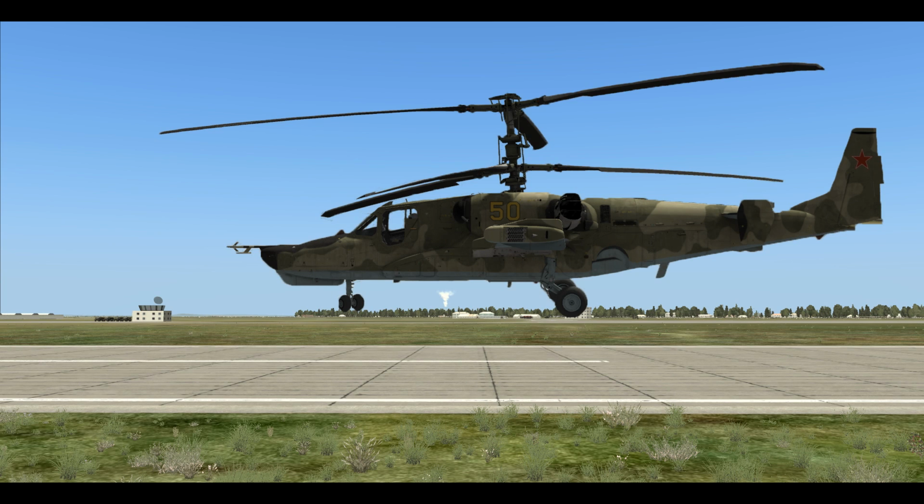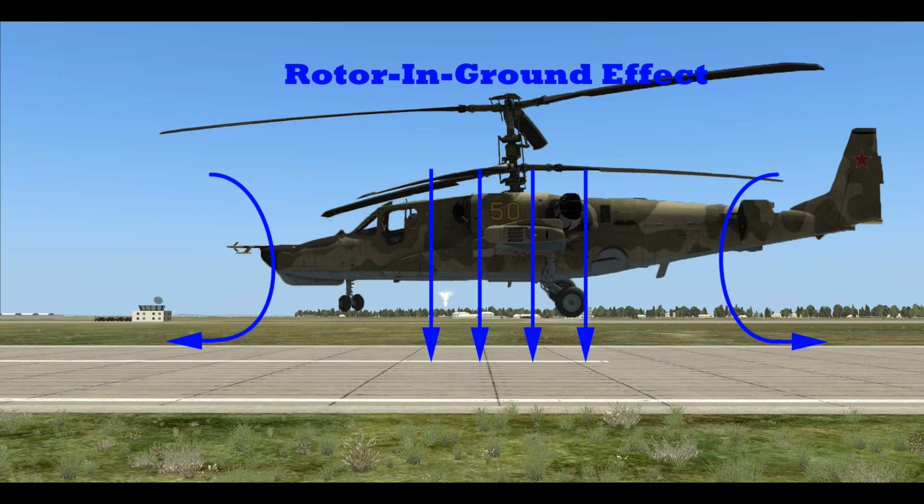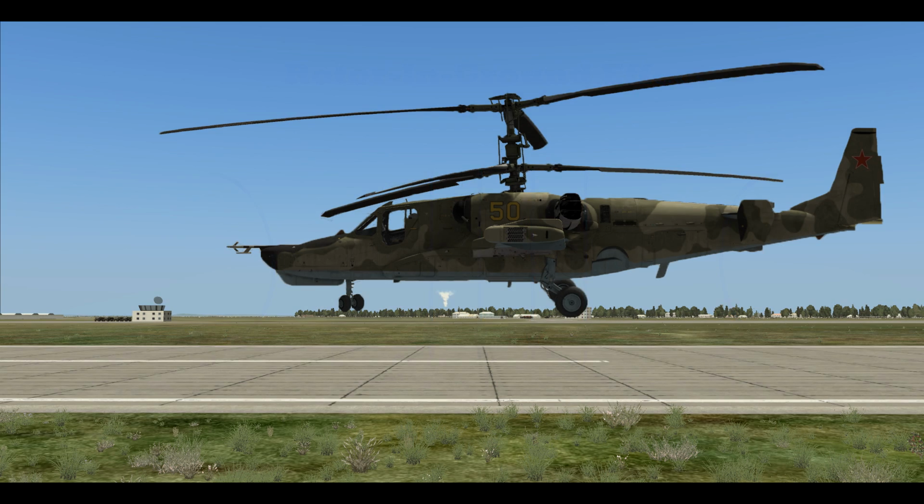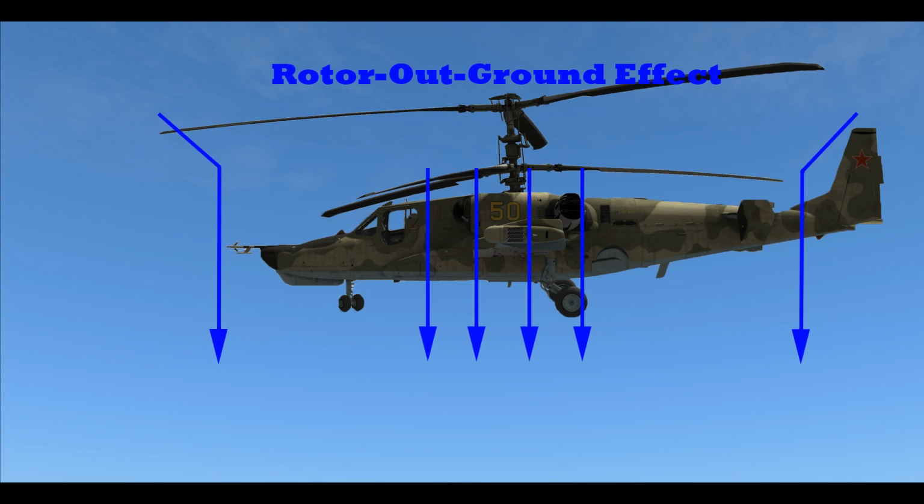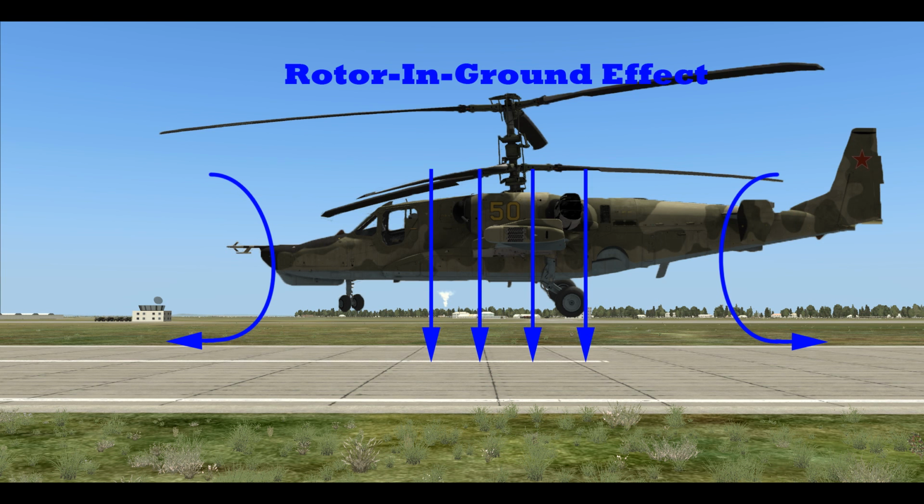Before we are taking off, let's briefly talk about this thing called ground effect. Ground effect is something that will happen when you come too close to the ground with your aircraft. The airflow is changed, it's not going down anymore, instead it's bouncing back from the ground, generating more lift for your aircraft. So you have to keep this in mind when you are landing your aircraft, since when you come close to the runway and you are inside the ground effect, you need to use your power to be able to actually land, instead of just hovering over the runway.